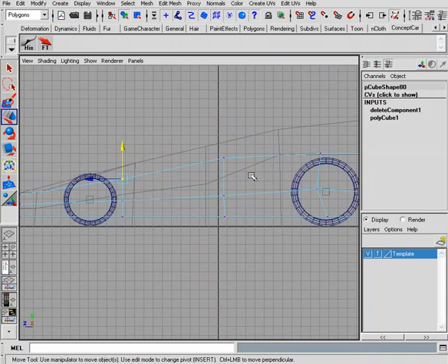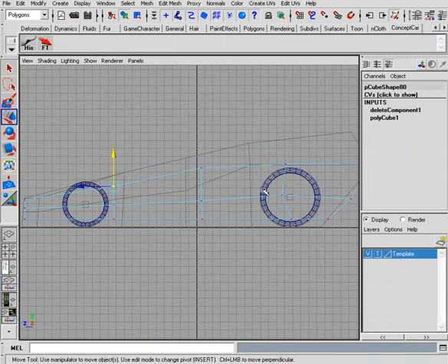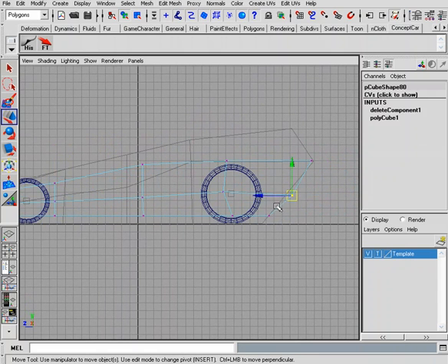But if you're going to be smoothing this, which we are, you're going to have to worry about the shape changing anytime you add resolution, because the smoothing algorithm is going to smooth between here and here, here, and here. And if you start adding resolution here, that shape's going to change a little bit. Now we're working at fairly low resolutions right now, so it's not going to bother us too much, but it will be something that we have to watch out for. So we'll just kind of shape this.